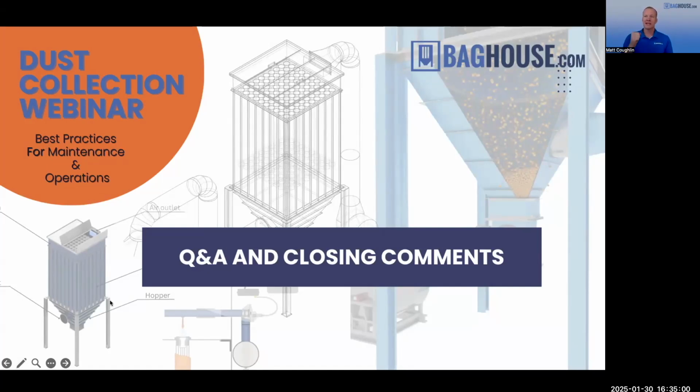You go into the clean air side or the clean air plenum of your bag house with the UV light, a black light essentially, and you basically play detective. You run it along until you find the indication of that powder where it's come through the filters. And usually you'll find that there's the filter. You can identify 2 or 3 spots. Sometimes you'll see around the interface between the filter bag and the tube sheet, there'll be a little indication.